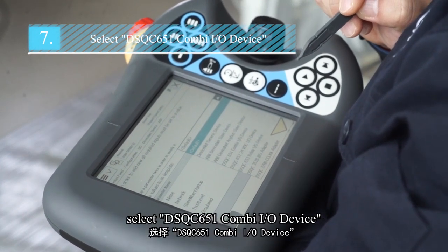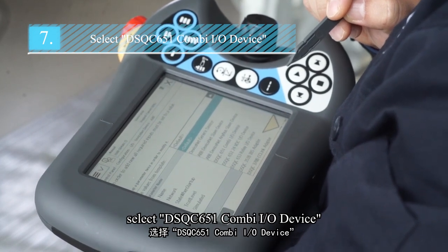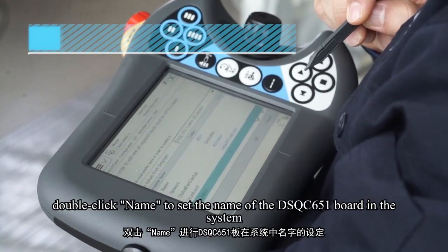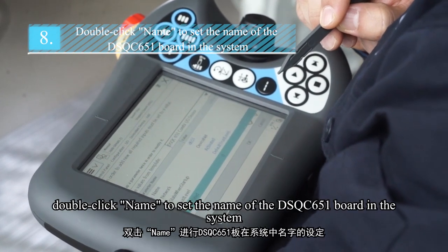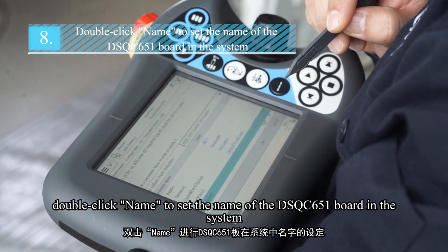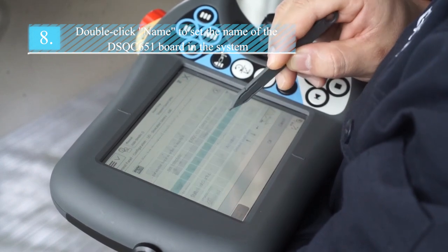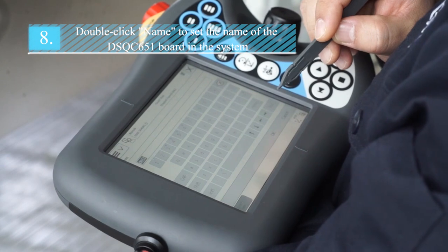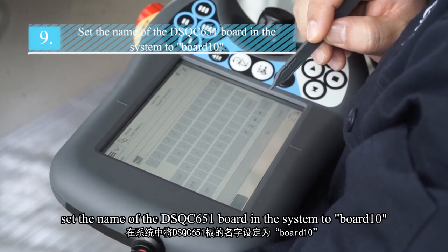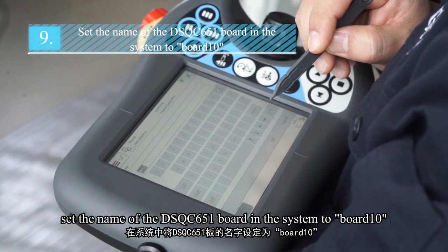Select DSQC651 Combi I/O Device. Double-click Name to set the name of the DSQC651 board in the system. Set the name of the DSQC651 board in the system to board 10.